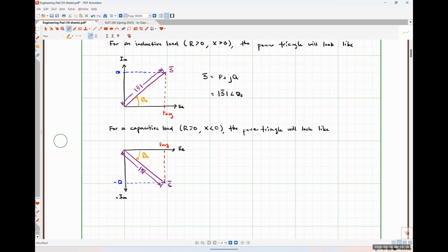The resistance, exactly right. So there is such a thing as negative resistance, but it is pretty darn rare. Devices that utilize negative resistance don't utilize it over their entire operational range, just for brief portions. The most common example is actually the ballast in a fluorescent light system.